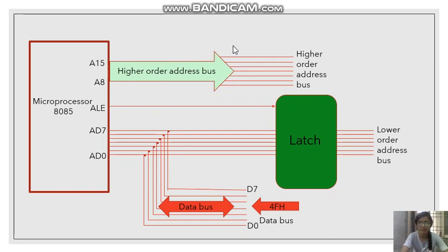It will work for the 3 T cycles in the timing diagram, whereas the lower address lines will carry the 05 of the location 2005, and will work for the first T cycle only. For the remaining 2 T cycles, it will get freed because it needs to be used as the data bus by our memory, because it needs to carry the data back to the microprocessor.